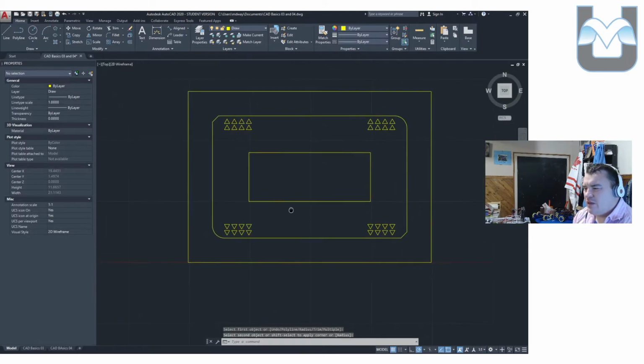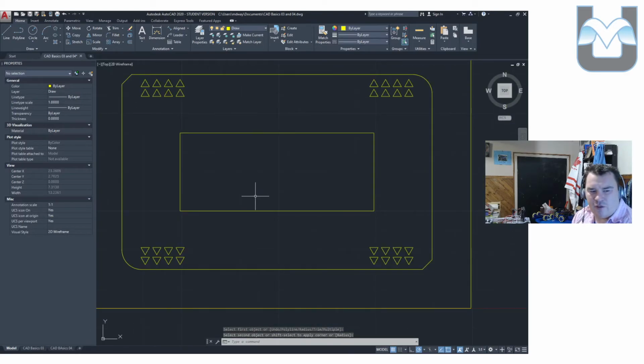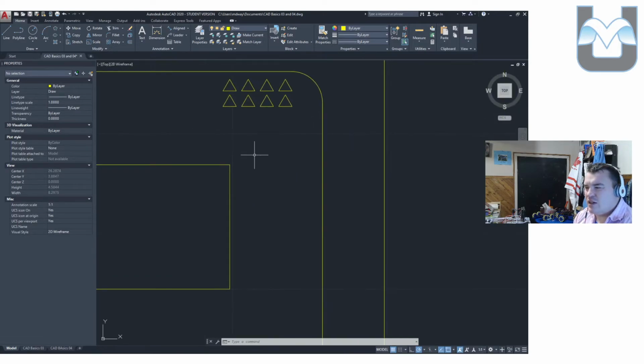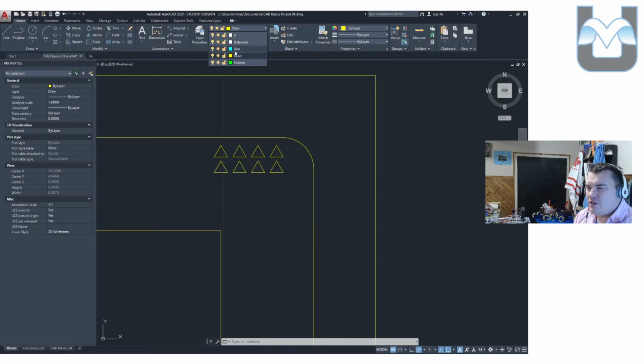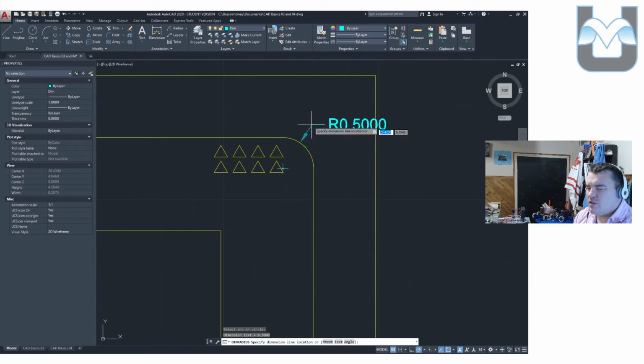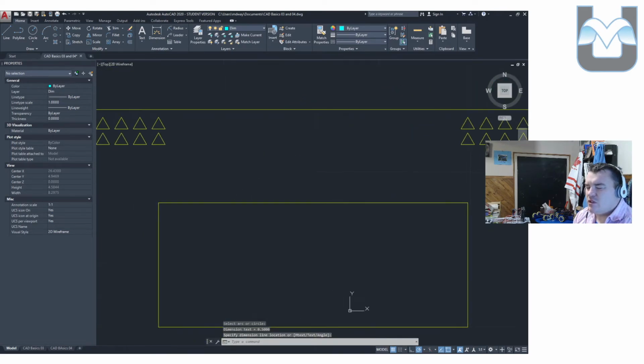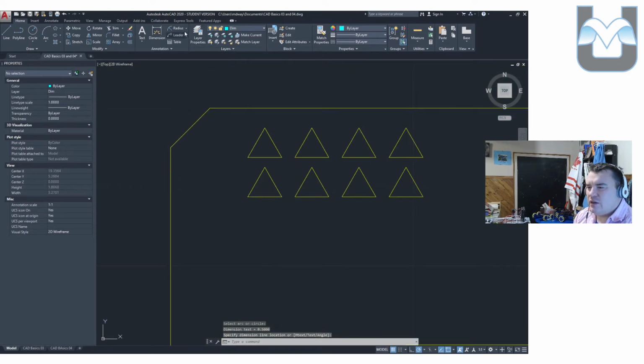For those of you that have taken the aviation class at Mandela, you know that all of your edges are rounded off to 1/8 of an inch, 0.125. So when I was doing some of the drawings for those projects, my fillet command was constantly set to 0.125. Anyways, now we've got some rounded edges, we've got some squared off edges. The nice thing with these is that when it comes to dimensioning them, they're super easy because we can put a radius dimension directly onto these ones, which is super nice. These ones need linear dimensions, but still.